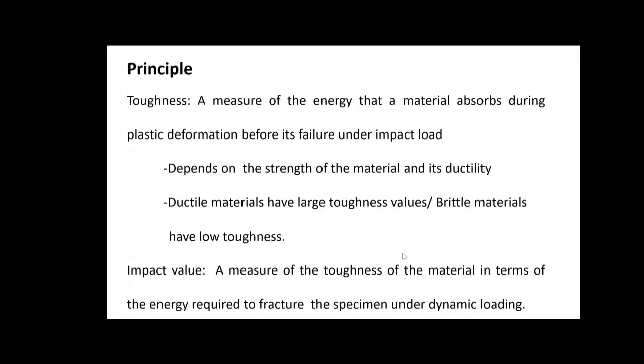Now coming to the term toughness. Toughness is a measure of energy that a material absorbs during plastic deformation before its failure under impact load. So this depends upon the strength of the material and its ductility. So ductile materials possess higher toughness values compared to brittle materials.